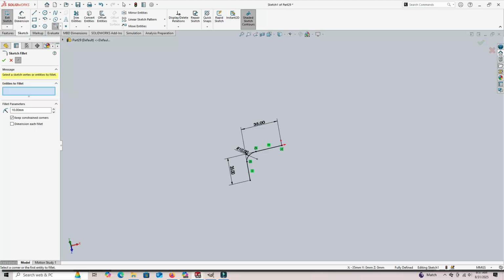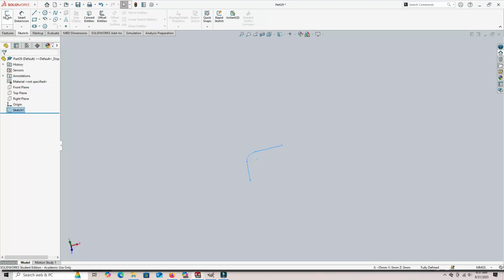At this point we are done with that sketch, so I'm going to exit the sketch up here in the top left. I'm going to click out in the field so that sketch is no longer highlighted. And at this point, in order to do my second sketch, which will be a line coming off this direction and then bending up, but also angling back at 45 degrees, I need to create a reference plane. And you'll find these commands in the Features tab up here.